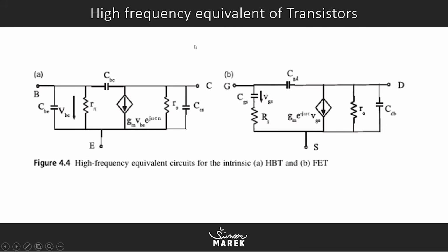So here's our high frequency equivalent of transistors. You can break down your transistor into a lumped elements representation, and you can exchange some components for some current sources, and you can simulate this, and from this you can see parameters of a circuit.